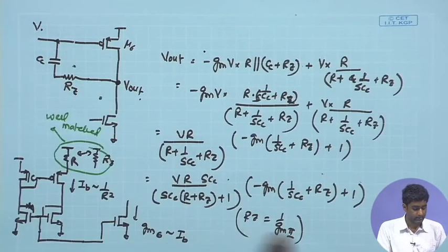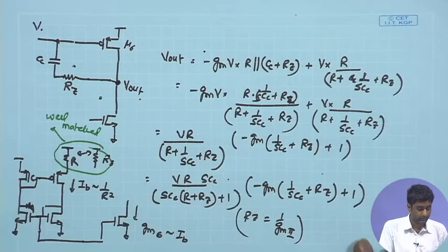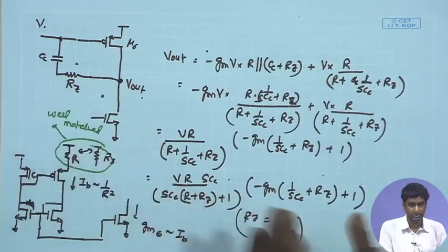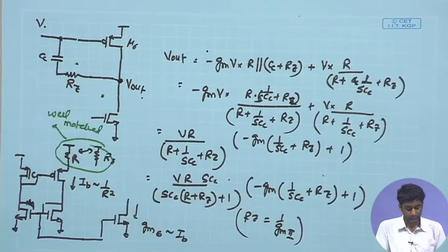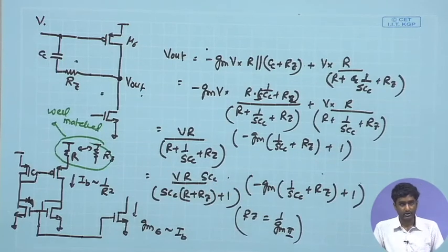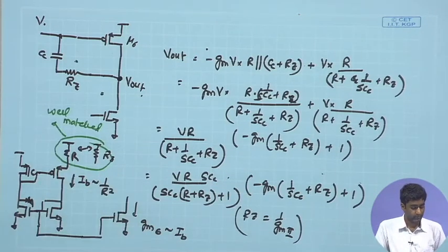Through that this cancellation can be made effective over a wide range of temperature and process variations, and we can ensure that the overall zero cancellation is achieved across process variation. So, this is another scheme that can be employed for the overall elimination of the zero in the circuit. Any question before we proceed further on the two schemes that we discussed for zero elimination?